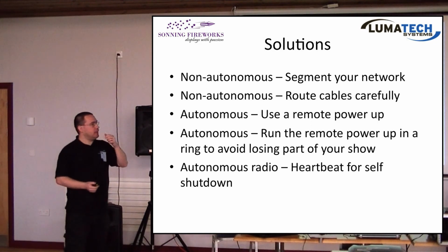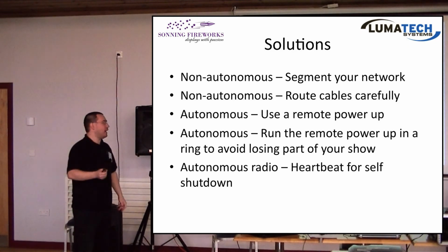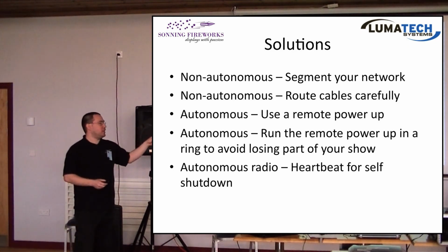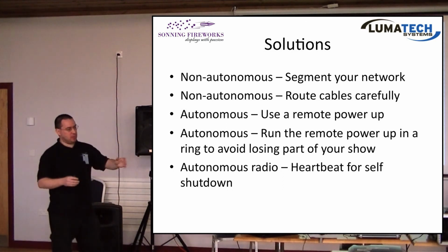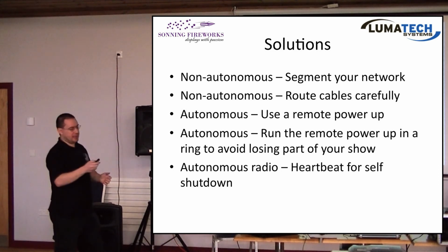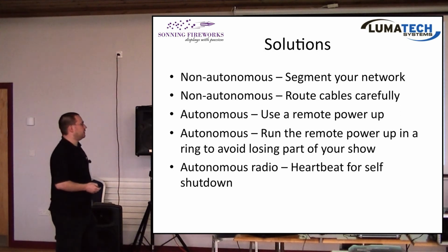With radio systems, of course, you haven't got a cable plugged in to physically shut it down. So what some companies have done, or are looking at doing, is using a heartbeat. The laptop will send out a pulse on the radio every so often, and the modules will carry on firing, and if they lose the heartbeat, then they automatically deactivate. And if they start receiving the heartbeat signal again, then they'll reactivate. So this is how, with a radio system, you can implement some kind of auto shutdown if it stops receiving the signal from the laptop.